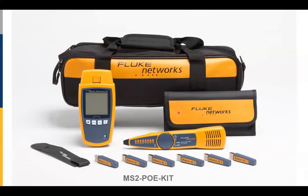But if I have to work day in and day out with RJ45 cables to support Ethernet in different customers' networks, or in my own network that isn't well identified, the MicroScanner PoE is a great solution. It's going to tell us continuity. How long is the cable? What's on the far end? It will tell me if there's a switch on the far end. It will tell me if the device on the far end is transmitting PoE and how much PoE is being transmitted. Today there are 8 defined classes of Power over Ethernet service and a handful of proprietary ones like UPoE.